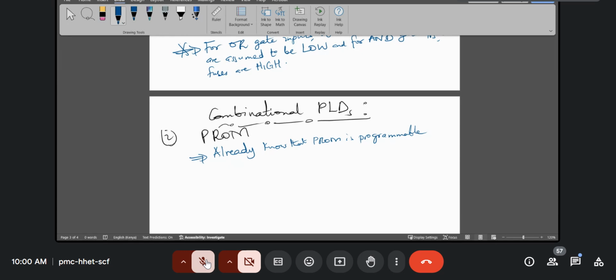In essence, that's really the PROM aspect as a PLD, that we can store some functions, not just zeros and ones as far as memory is concerned, but also functions that we are able to permanently execute because they are already programmed and hardwired into the device by blowing or leaving certain fuses intact.